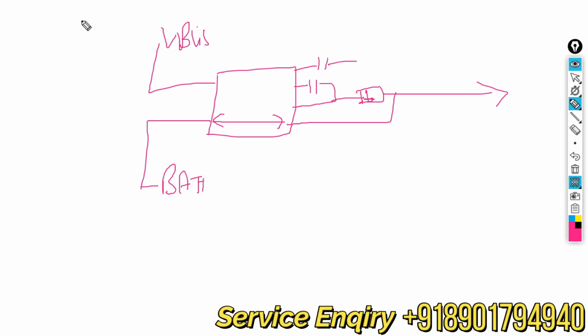Clear? So what happened? This IC has multiple MOSFETs, right? So one of the MOSFETs right here is leaking. The charging IC does not short properly, it has an internal leakage. So your charging, depending on the charging section, does not work properly.